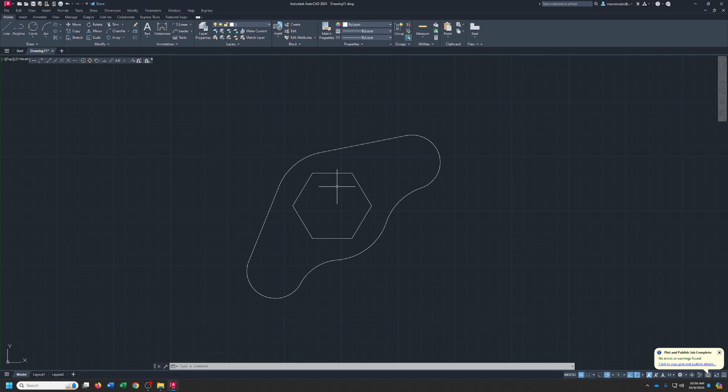Now it's going to want a square on the top and a circle on the bottom, and they're both, basically, the radius is going to be 10 on both of those. So we'll do the circle first because that's easy, right? So we'll go back to circle, we'll go to radius, center point of this, and 10. And there you go.